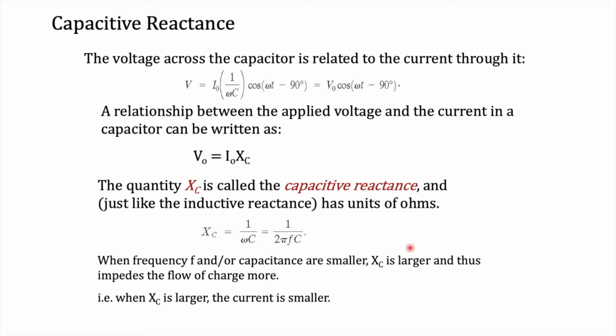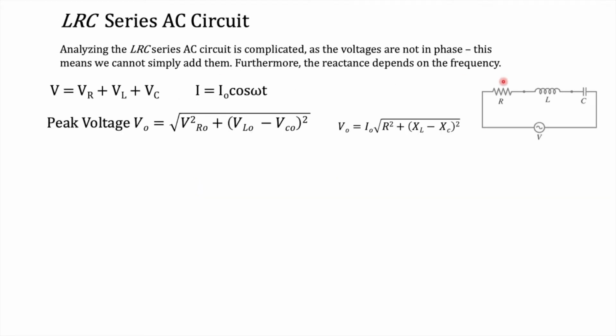And so we looked at the resistor, inductor, and capacitor separately connected to an AC source, and you saw how the voltage and current lag and lead in each of these elements. These are called elements: resistor, inductor, and capacitor. And we can add all these together in series to the AC source. The change in potential around the loop is still equal to zero from Kirchhoff's law. There is a potential change here, here, and here in each of the elements.